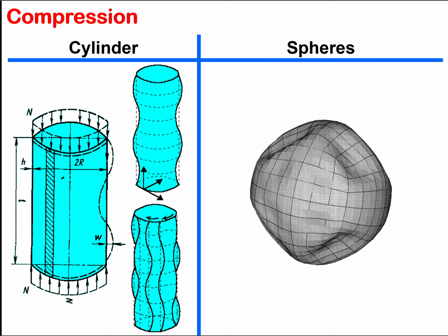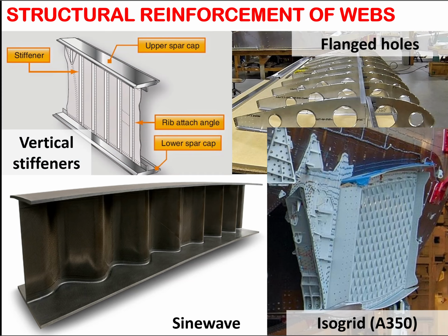Okay, we can have plate buckling on cylindrical shapes and spherical shapes by applying a compressive load or a shear load, and the idea is that analyzing all of these analytically is basically impossible. We have a couple of empirical equations, but we don't really have a real deterministic model to measure the buckling load for plates or spheres or cylinders.